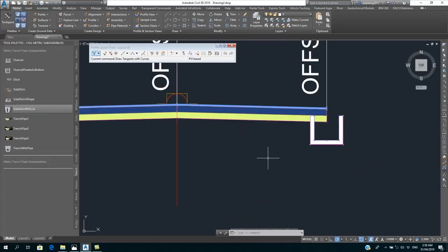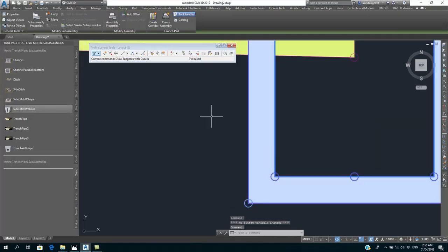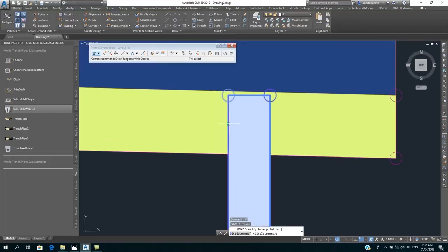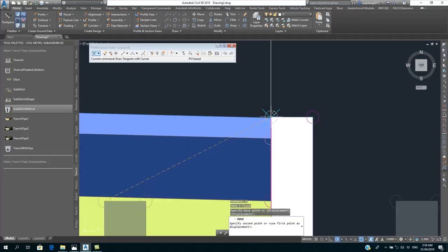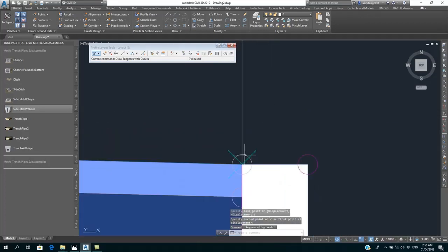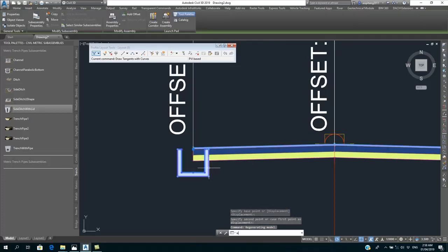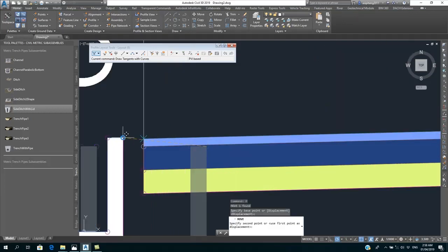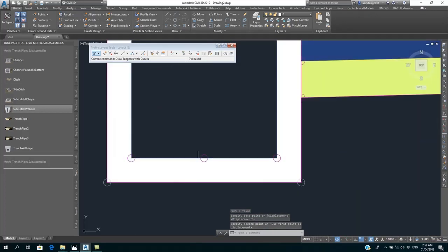Now to put it at the exact positions, the drainages have what we call the ribbon, the connecting line for each sub-assembly. You can see I move it and connect those lines, the connector, to position it and match the sub-assembly details so I can have your assembly information. You can see it as reference at the edge. So every other piece of information can be built out as such, but we're just using this to explain the simple procedure of working with this. So this is my assembly build-up with detailed information. At this point, I need to get the invert level for my drainage alignment.